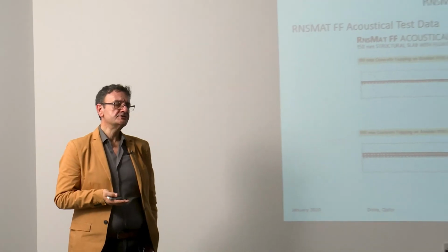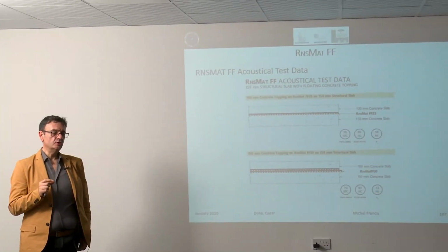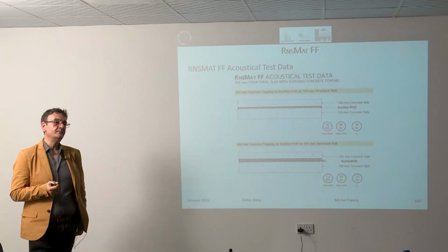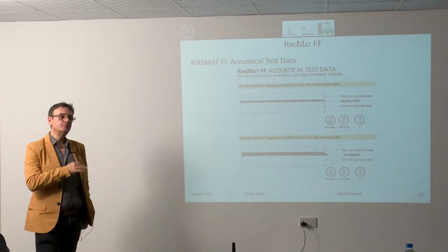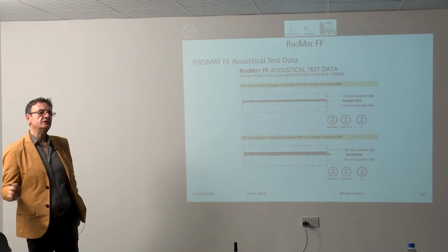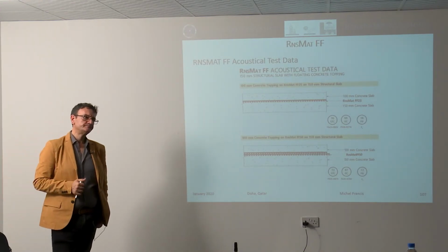That concrete is just to isolate whatever is giving sound above. Whether it's an electric or electromechanical equipment or it's a football field, it's the same thing. It will be covering the whole room or the particular area of the mechanical equipment. This is what we call the inertia pad. The inertia pad's work is to isolate vibration mostly. But if you want to make an absolute cut of the sound, then you need to do the whole roof.